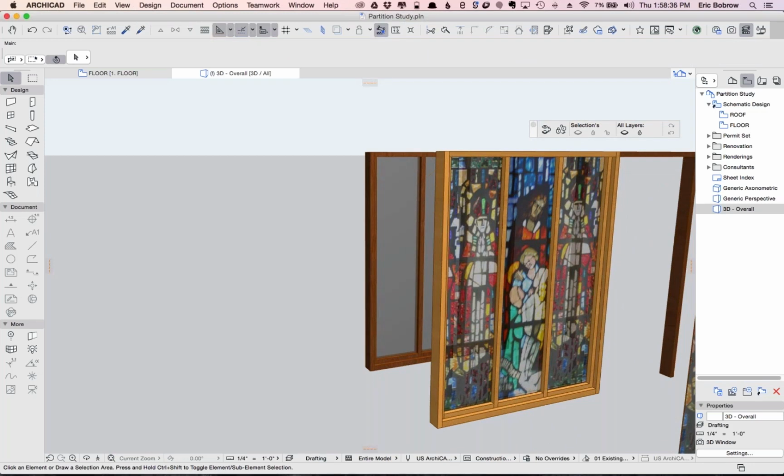Yeah, I was thinking maybe just like the art class. Let's say I found a texture of a piece of wood online or something, and I wanted to apply that specific texture outside of the library. Would I do something similar to the art class? I would create a new surface material, import that image, properly scale it, and then apply it. That's correct. Now, one of the issues with a texture that you're going to apply to a broad surface is that when it repeats, it's likely to show tile marks.